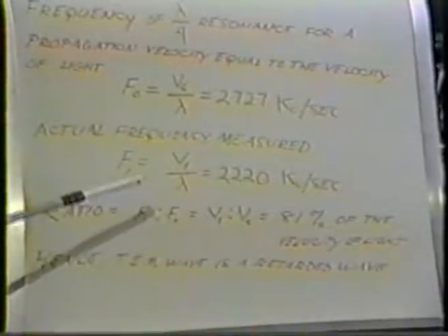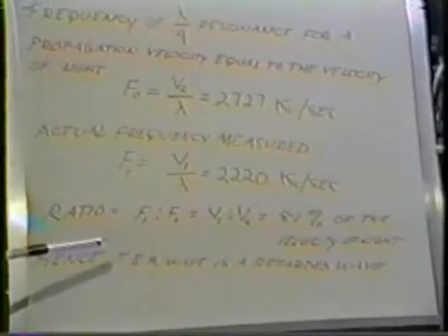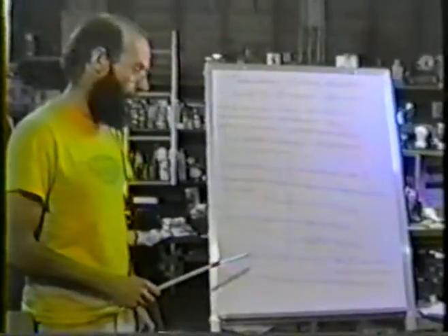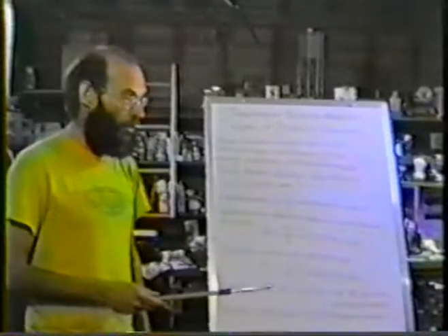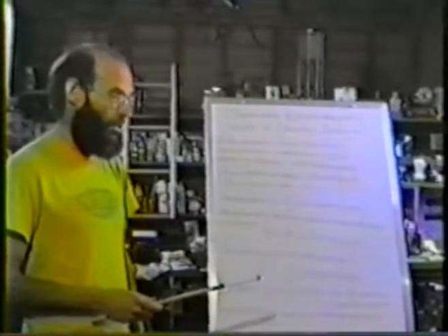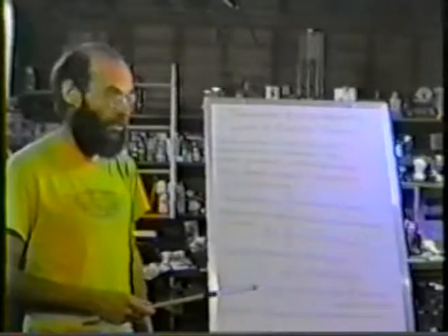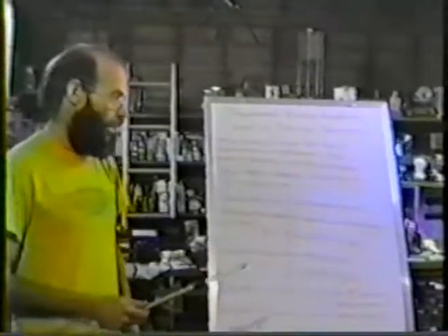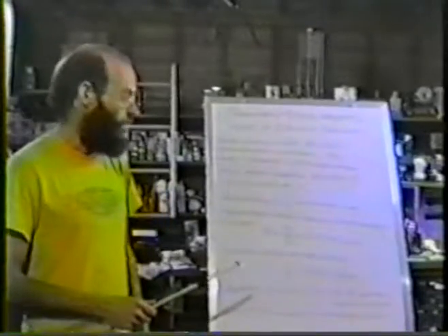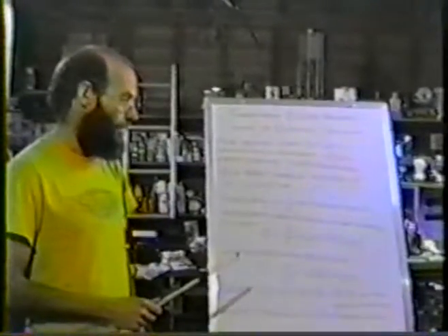Hence, this transverse electromagnetic wave is a retarded wave in that it propagates at a velocity less than that of light. Now, the reason for this retarded propagation velocity is due to the fact that the velocity of light is slowed down by the translucent medium that fills the cable to insulate it, and the resistive losses and conductive losses of the cable in general also tend to slow down the wave a little bit. Now what we're going to do next is go to the longitudinal wave and show our test setup, do our measurements, and perform our calculations on this wave.